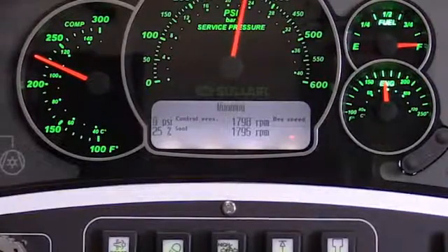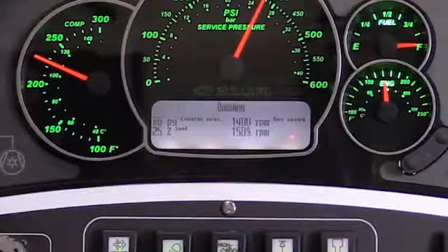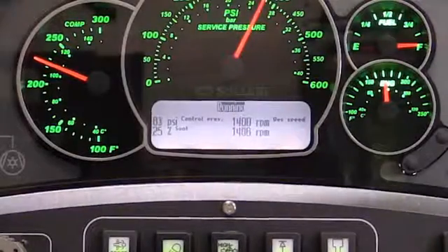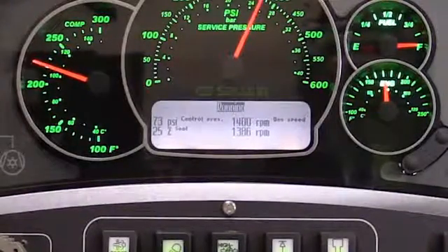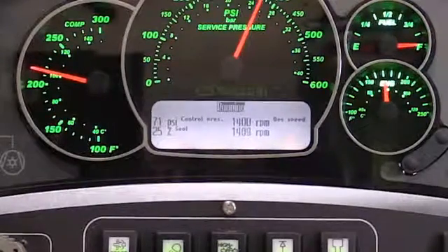Shown here, I'm closing off the ball valve. This simulates the operator's demand on the machine going down. We're going to go back to the unloaded state where control pressure will rise, the inlet valve will close, and RPM will subsequently drop to minimum idle RPM.